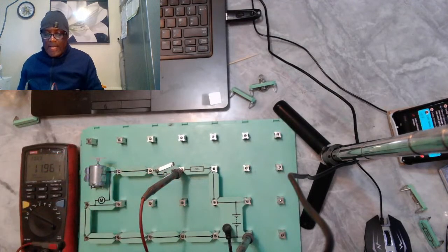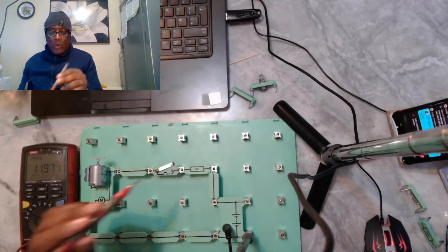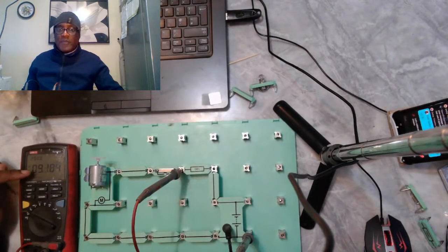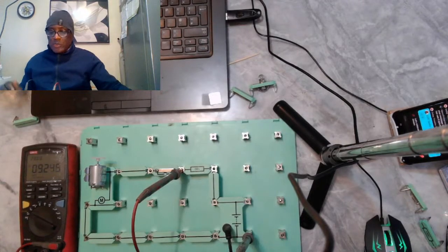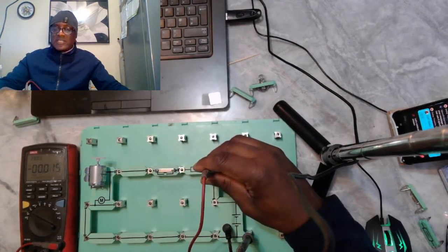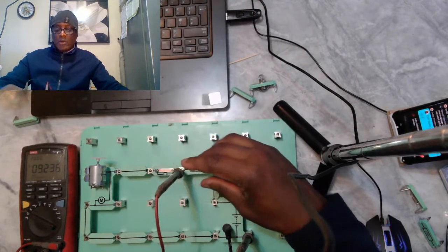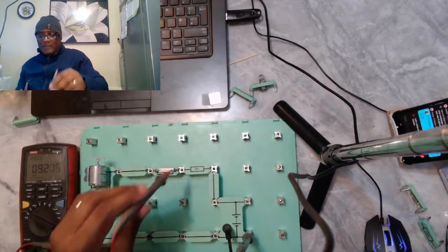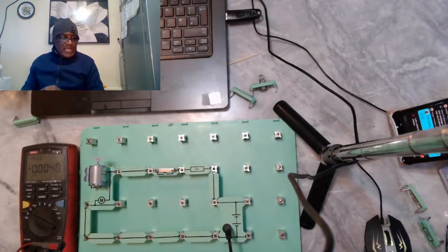we can actually investigate and see what is causing it, what the voltage drop is. We've dropped from 11 to about 9.2. So let's investigate this point where we are getting battery voltage, and that point when the battery voltage has become lower. All right, so that's the effect of resistance in a circuit.